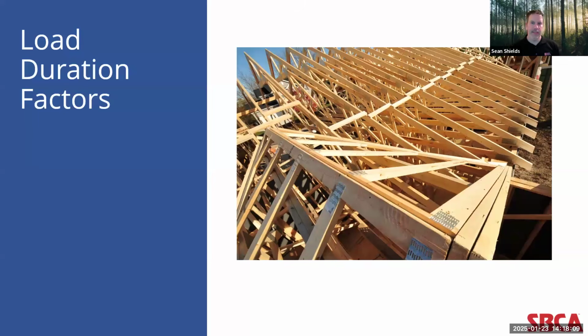The next thing to look at is the load duration factors, or LDFs, used in the design of the truss. Load duration factors are used in truss design to account for the effect of a given design load's duration on the strength of a structure. The reason this is done is because wood has the ability to handle higher stresses under shorter periods of time. Now, again, I don't want to get too much into the weeds on this. You can write very long, engineering-based white papers on just one of these LDFs.